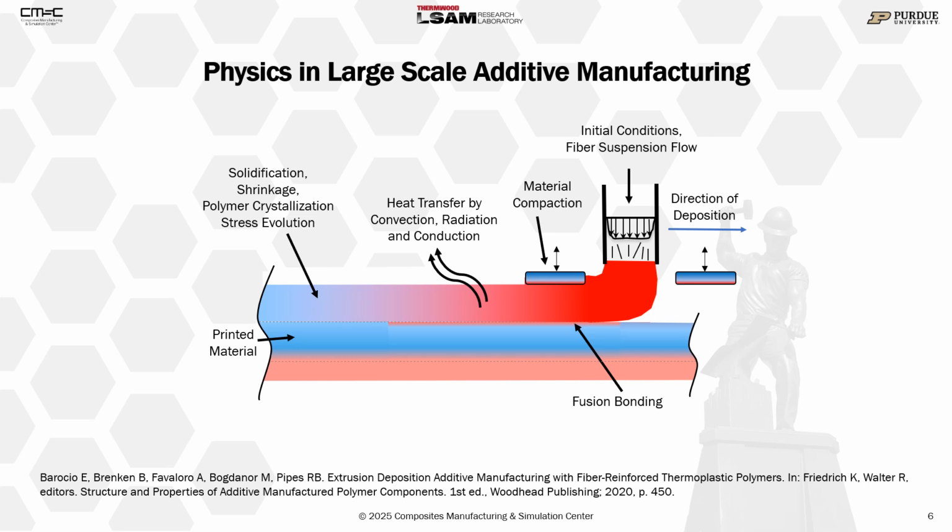And on the second hand, we also capture the stress relaxation that the polymer exhibits at elevated temperature through an isotropic thermoviscoelastic material formulation. And then the last but not least important, we have different modeling techniques to capture different types of build plates or substrates, on both the thermal as well as the mechanical interactions of the printed material with the substrate.